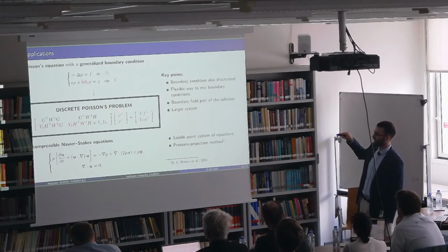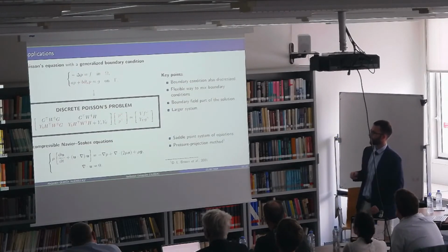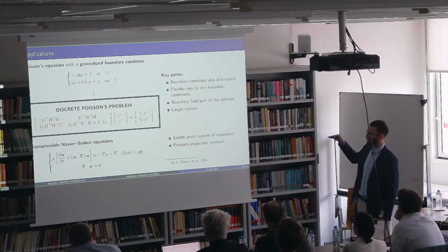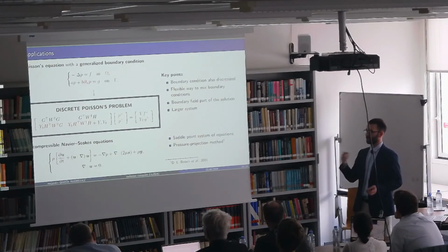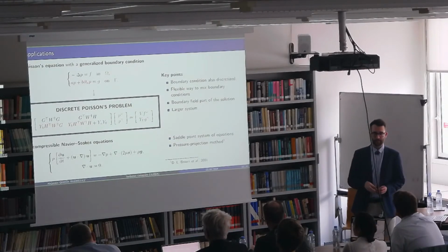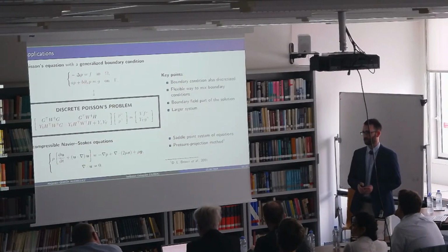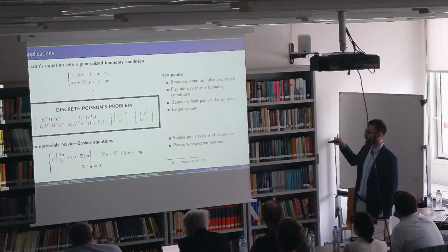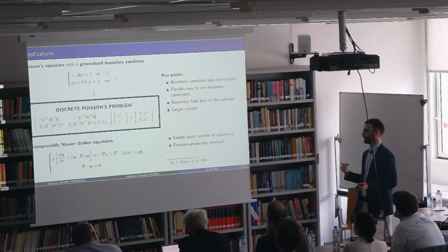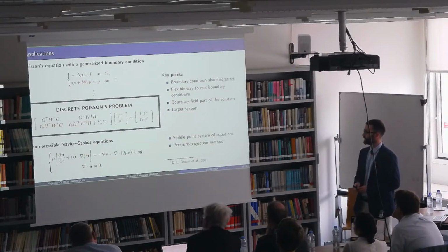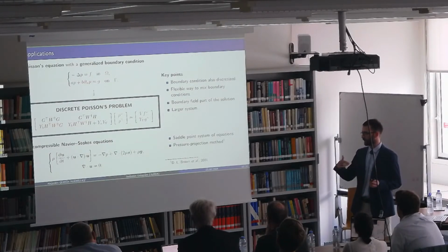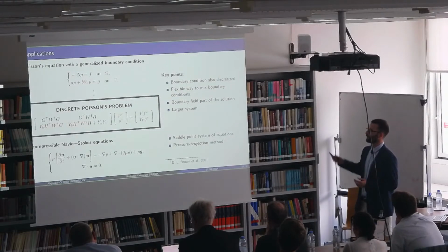Then you can see here that in the solution vector, we have two different components, P omega and P gamma, where P omega is the vector for the bulk field and P gamma for the boundary field. This means that as part of the solution to our problem, we obtain the values at the boundary field. And this removes one source of error because now we don't need to interpolate or extrapolate the values at the interface from the bulk field, which is very convenient for many applications in interfacial flows which require the use of values at the boundary. But of course, all of this comes at the cost of having to solve a larger